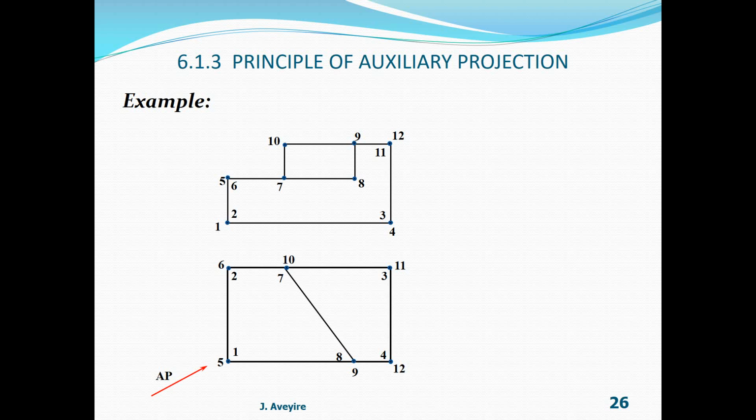The result of this projection is going to be a first auxiliary elevation. Now we need a mutual view. The only mutual view provided here is the front view, therefore MV is the front view. The mutual projector is a projector of our given view such that the result is the mutual view, and that is MP.